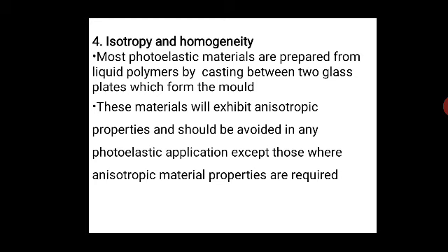When the photoelastic materials are prepared by the casting process, the molecular chains of the polymer are randomly oriented, and the materials are essentially isotropic and homogeneous.